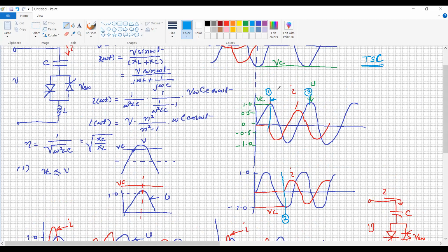The reason is that the switching of the capacitor may start at the peak value of the voltage in the positive cycle, the peak value of the voltage in the negative cycle, or from the next peak of the voltage waveform, isn't it? Hence, no delay angle is provided in the gate pulse, and therefore the thyristor switched capacitor is possible. Thyristor controlled capacitor is not possible. This is a very important point.